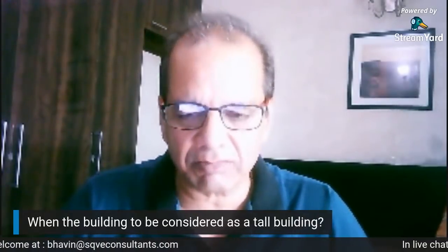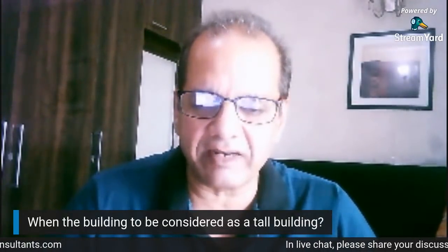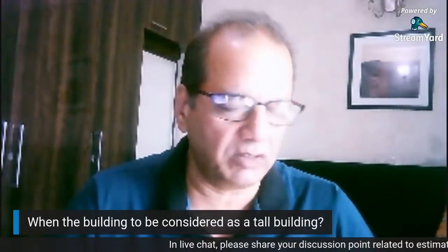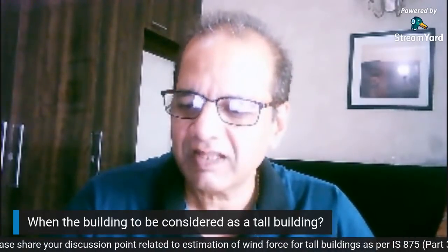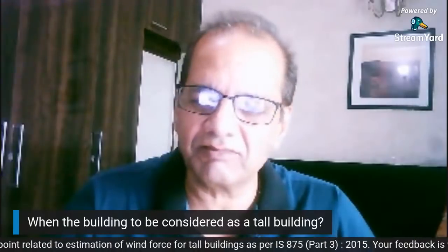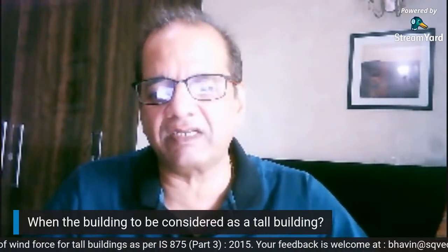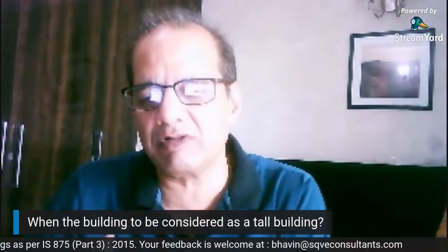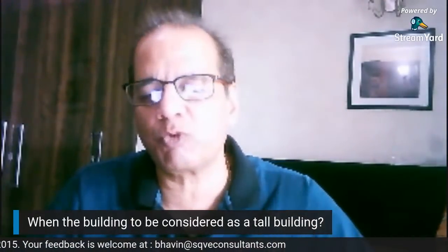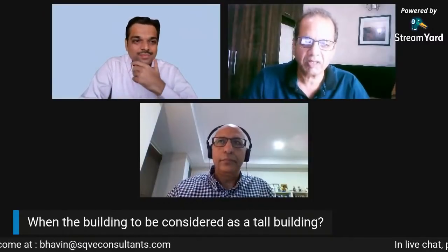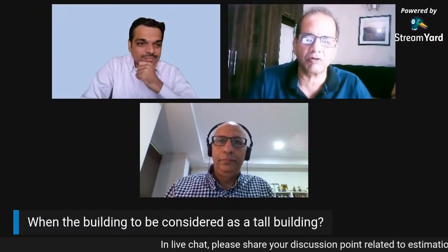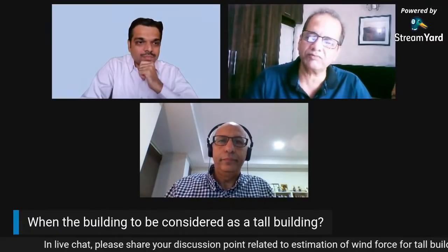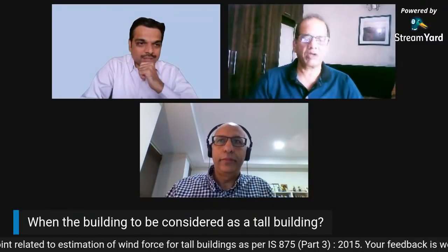Now, everybody who is a user or designer may have a question. Suppose a building is 50 by 15 in plan and 50 meters high, should it be called a tall building? As per IS 875, it doesn't qualify. But as per IS 16700, it qualifies. So probably those points can be taken up in future. But as of now, a building of 10 by 10 by 50-meter height would certainly qualify as a tall building. And for any building more than 50 meters, there can also be engineering judgment depending on the plan dimensions. Okay, we move on.